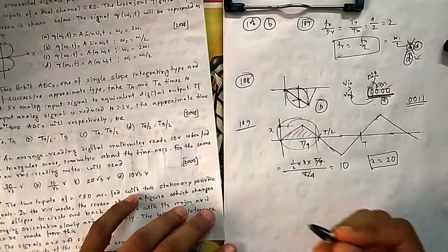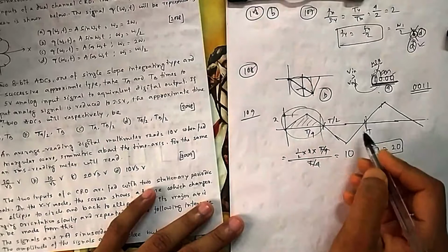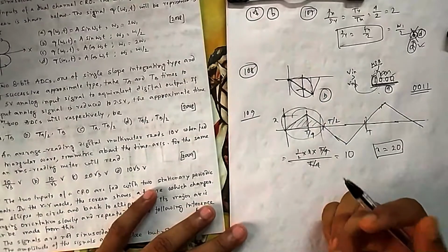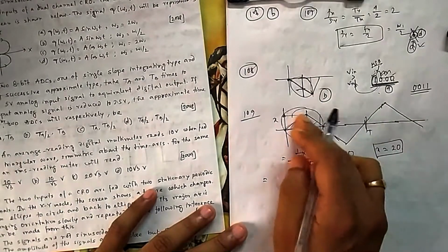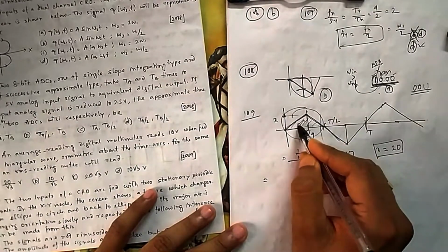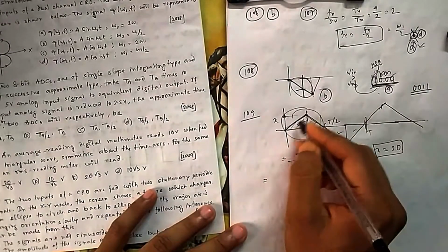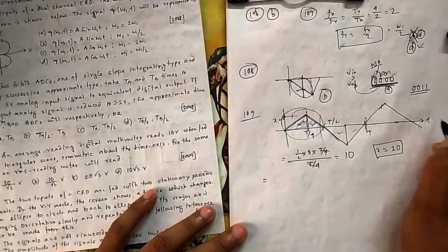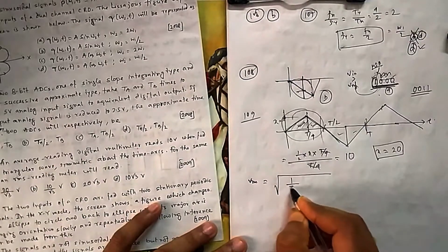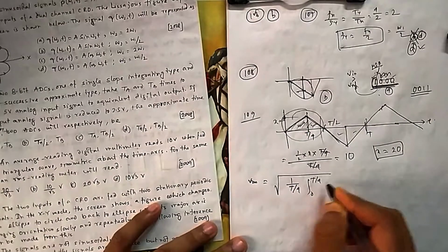So now, once you know x equal to 20, you can find the RMS value also. For RMS, you need to integrate it from here to here. But if you integrate up to this, it will be the same, because if you square it, negative will also be positive. So I take only this portion, 1 by 4, because the rest are symmetric. The way it is increasing, the same way it is decreasing. So each triangle, this triangle, this triangle, all are the same. If you square it also, everything will be the same. That's why I am doing only this one. This height is 20, and this is T, suppose. So what will be its RMS value? It will be under root. Take the average up to this much, 1 by 4, and then integrate from 0 to T by 4, and then square.